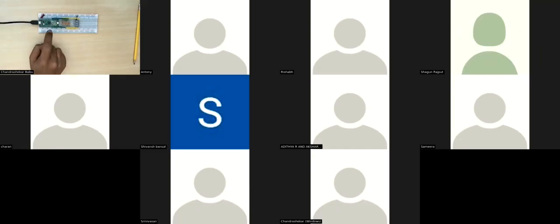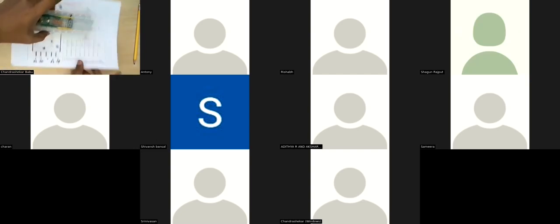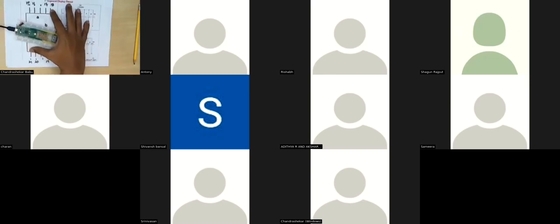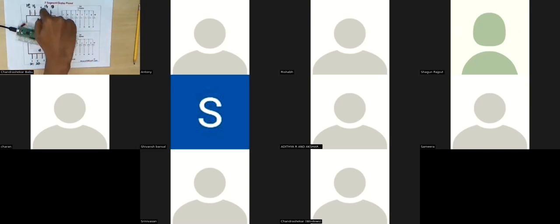Last class, if you remember, I showed how you can control a simple 7-segment display using MicroPython through Raspberry Pi Pico. We in fact did the wiring and everything, right? And I showed you what a 7-segment display looks like. You see here, we connected all these pins. I noted down the pins that we connected on the Raspberry Pi Pico to the 7-segment display through these dropping resistors. And we also wrote a program to control it.